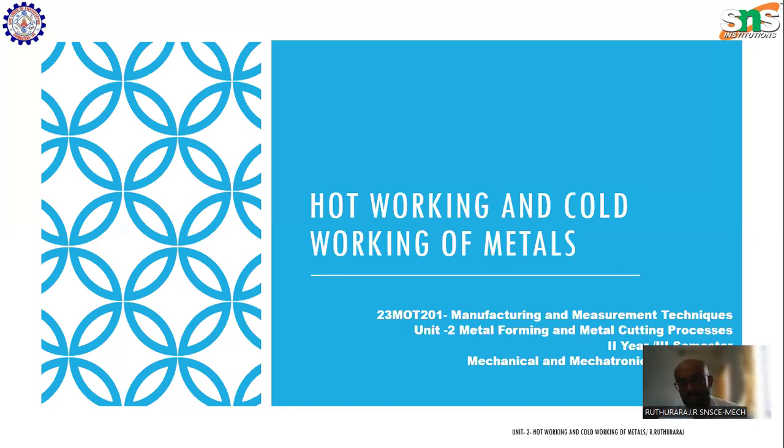From the previous lecture, we can see that any material which is manufactured using a casting process tends to be brittle in nature. So if you have to use those parts which are manufactured using casting in load bearing applications, then you have to change the properties of those materials. That can be done with the help of a metal forming process.